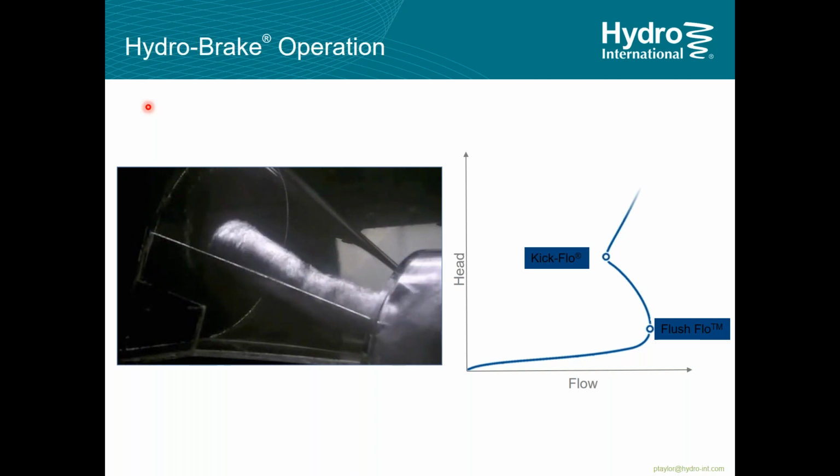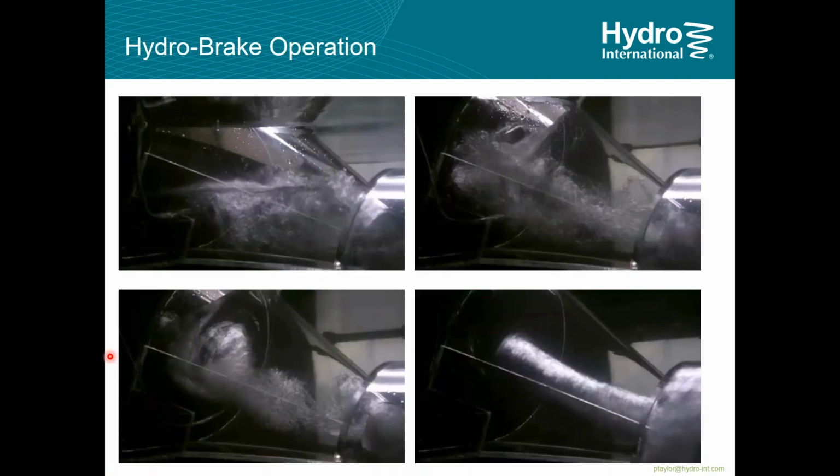So in the initial stages, these valves have a large opening and the water can pass through quite freely. But as the head builds up, they actually slow down. So you actually get a decreasing flow with an increasing head. And that's the crux behind the valve. That head discharge curve is unique to a vortex flow control valve. And it's that discharge curve which gives us many of the advantages of using these valves over standard orifice controls or throttle pipe controls.